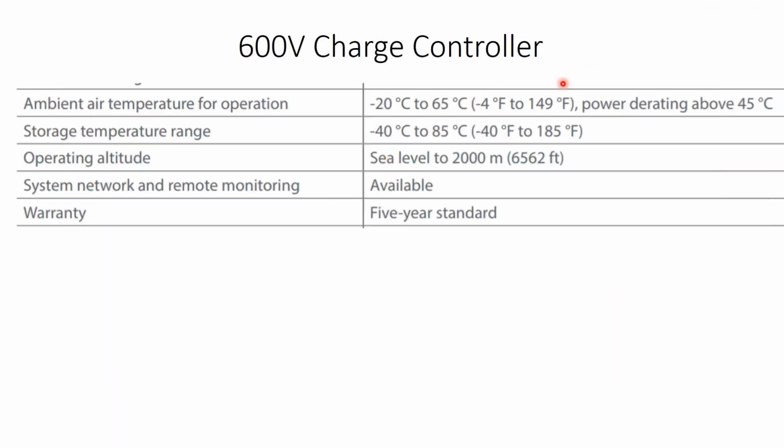I actually think that if you go and you read the manual, they say 90 degrees Fahrenheit in the manual for power derating. So your battery inverters, generally you want to keep them in a dust-free, air-conditioned environment. They're not the hardy outdoor NEMA 3R inverters that you see in the solar industry.